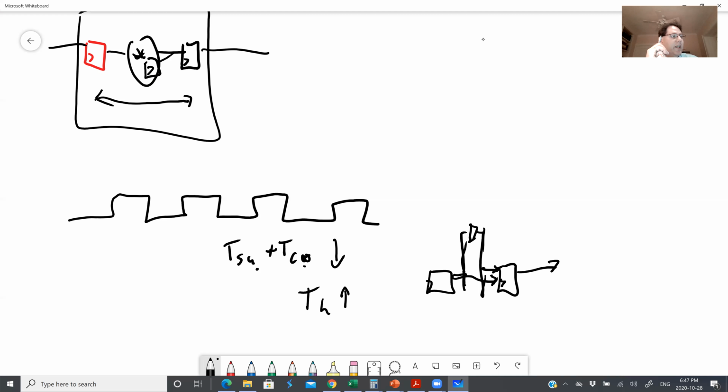It definitely does put pressure on the CAD flow. FPGA routers do have pretty good hold time violation resolution code, and it makes them more complicated. Commercial FPGA routers are more complicated than most of the papers you'll read on FPGA routing because they have to deal with hold times as well.